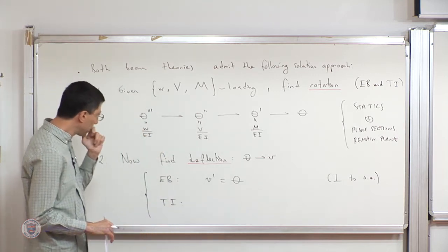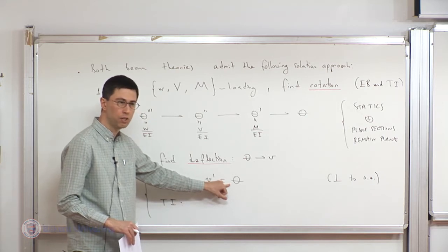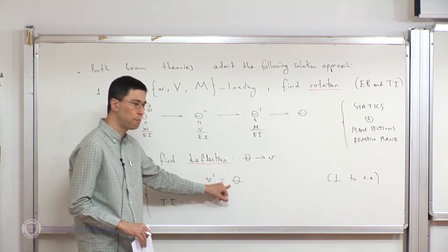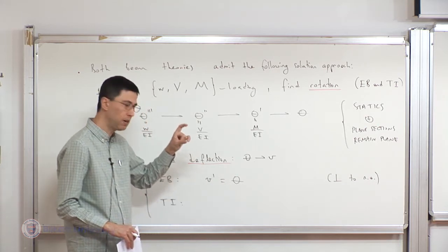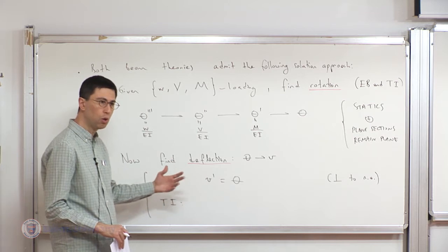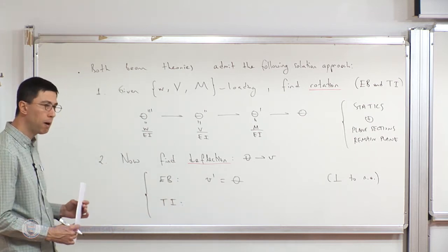Well, so this is equivalent to saying that we are omitting the influence of transverse shear stresses on deformation. That is not entirely correct. If the height of the beam is not very, very small, for sure it will cause some influence on the vertical deformation. So I need to somehow account for that.